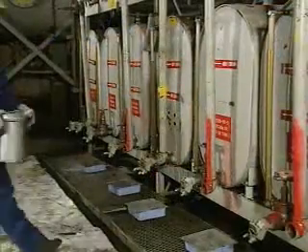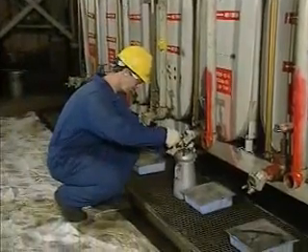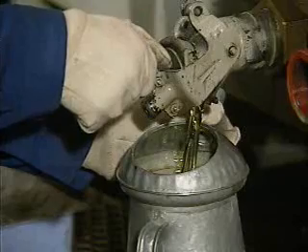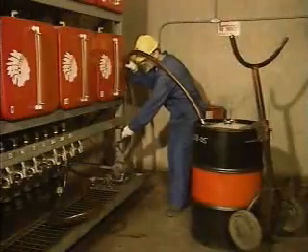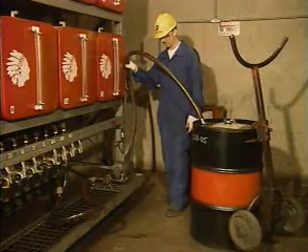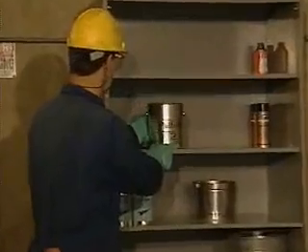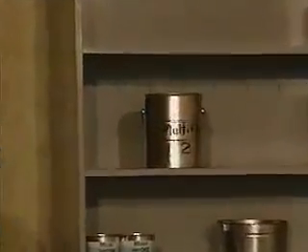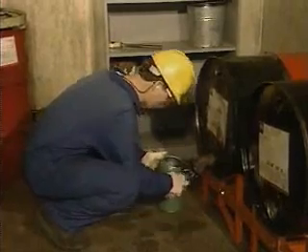To dispense lubricant from a drum by gravity flow, store the drum in the horizontal position on a rack and equip the drum with a spigot that has a drip-proof valve for withdrawing the lubricant. If you must store a drum in the vertical position, you'll probably have to pump the lubricant out of the drum. Store cans or pails of lubricant neatly on shelves or on the floor. Finally, repair leaks promptly and clean up any drips or spills immediately.